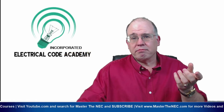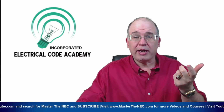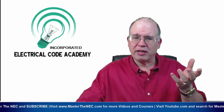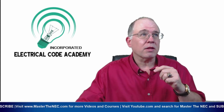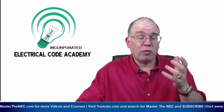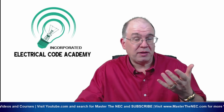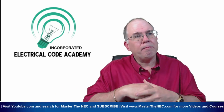We've covered a lot. We talked about the terminal limitations. We talked about the breakers and how important their role is, and we saw how that played out. We looked at all the other aspects of adjustment and corrections, nipples, and when you can avoid, when you don't have to account for the adjustment. You still have to worry about the ambient. We talked about the MC and AC cables and when you can discount and not use an adjustment. But we also looked at when you have to use an adjustment. And if none of those conditions apply, you've got to apply an adjustment or correction. We looked at all that.